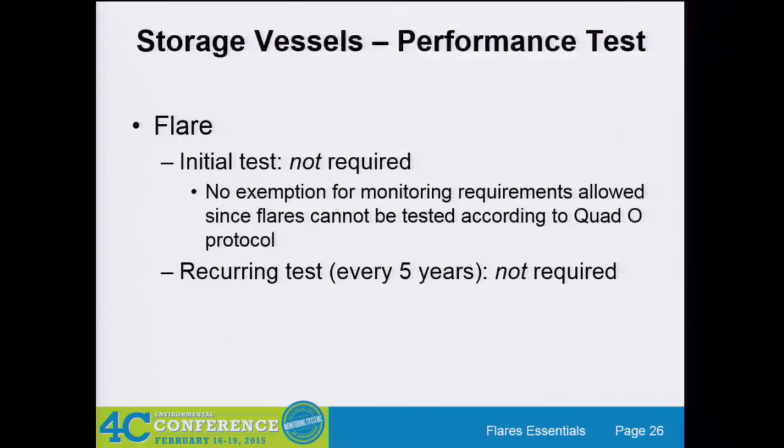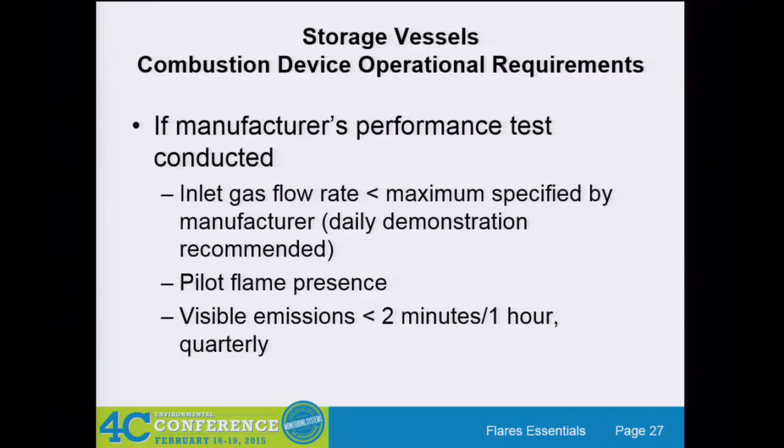Flares. Again, for storage tanks, initial test is not required. There's no exemption for monitoring requirements since flares cannot be tested according to Quad O protocol. Again, recurring tests not required. So they really backed off from the performance tests. If you use a manufacturer's test, you're good.